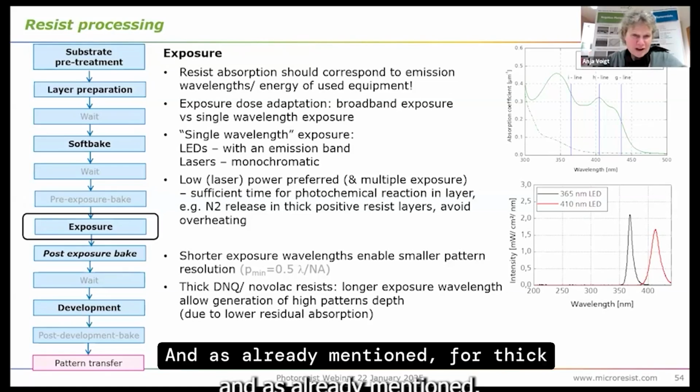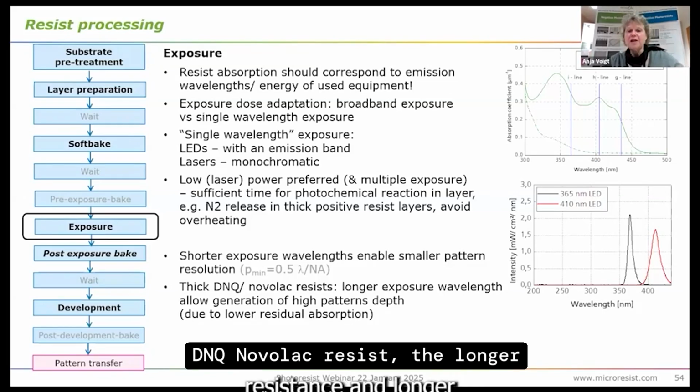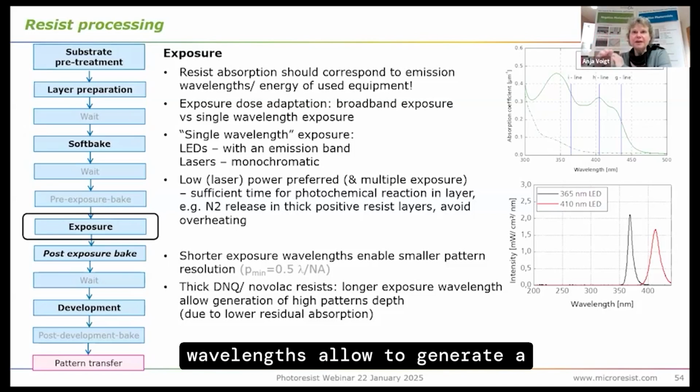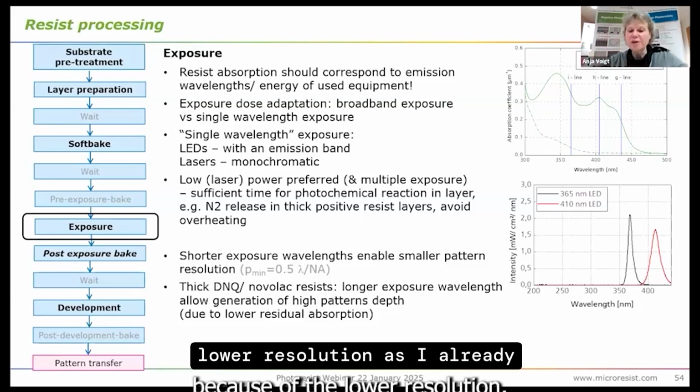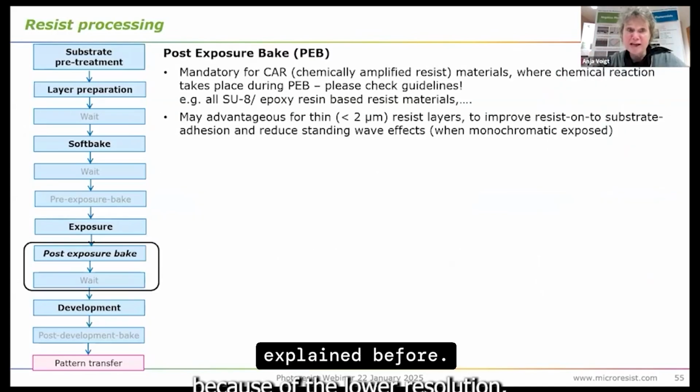Shorter wavelengths enable smaller pattern resolution. And as already mentioned, for thick DNQ Novolac resists, the longer wavelengths allow generating a deeper pattern depth because of the lower resolution, as I already explained before.